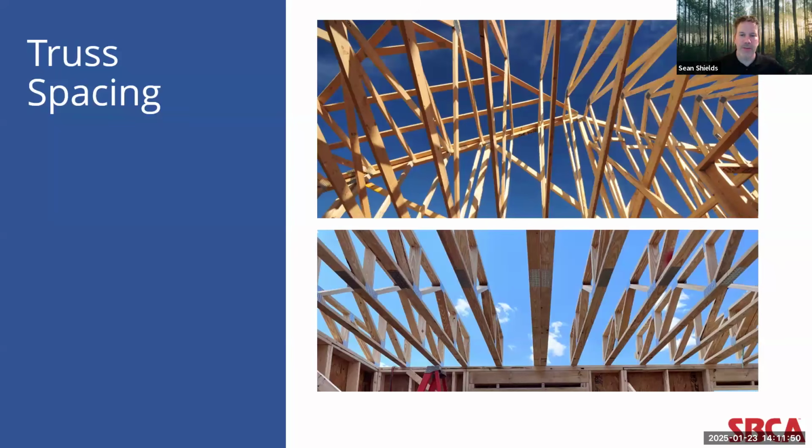Now, while theoretically the truss spacing can be any distance at all, the measurements I mentioned specifically are typically used to allow for the most efficient application of today's standard sheathing products that measure 4 feet by 8 feet. This, of course, allows the seams between individual sheets to line up over the center of each truss.